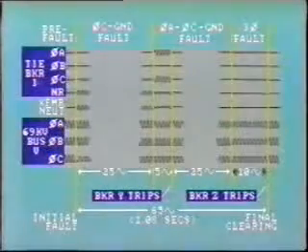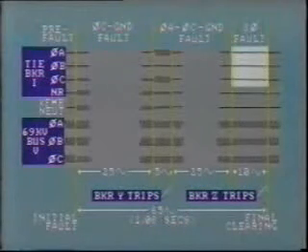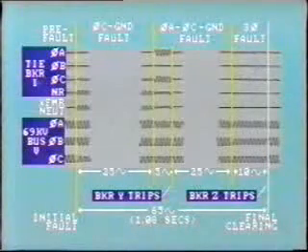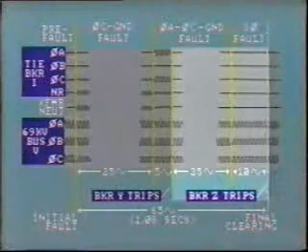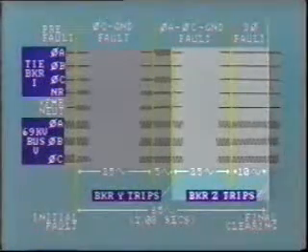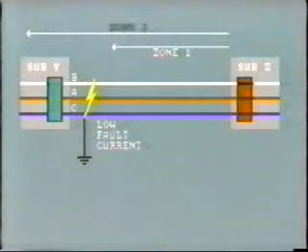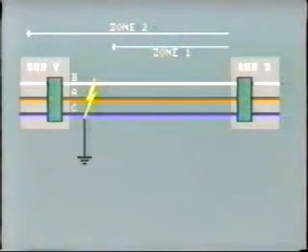For the next 10 cycles, we have a balanced 3-phase fault. You can see this from the 3 fault currents in the tie breaker and the fact that neutral and residual currents are now 0. Breaker Z at the other end of the faulted line now trips to completely clear the fault. This occurs 35 cycles after breaker Y trips. Again, this is reasonable because the fault current is low and also because the fault is in zone 2 of breaker Z's protection. Thus, tripping is further delayed.